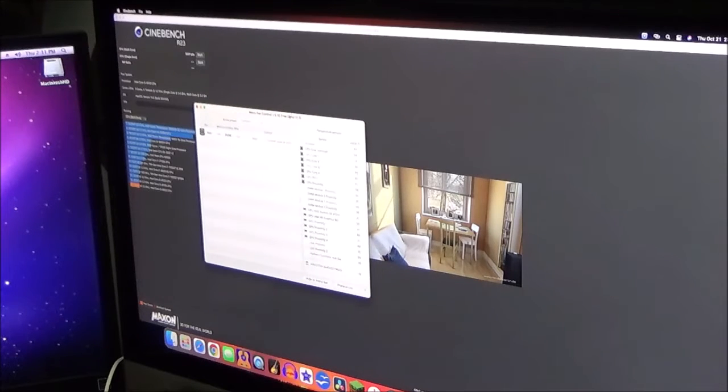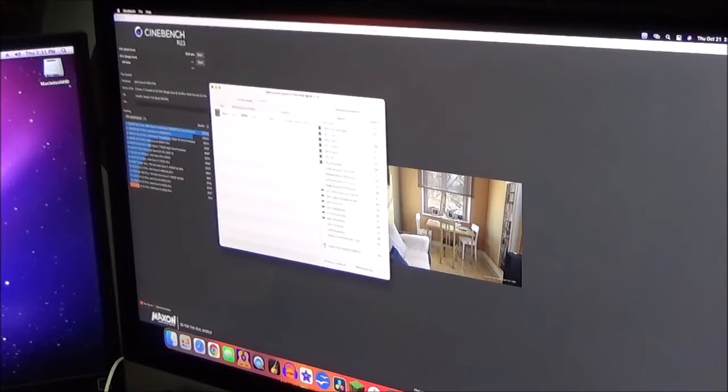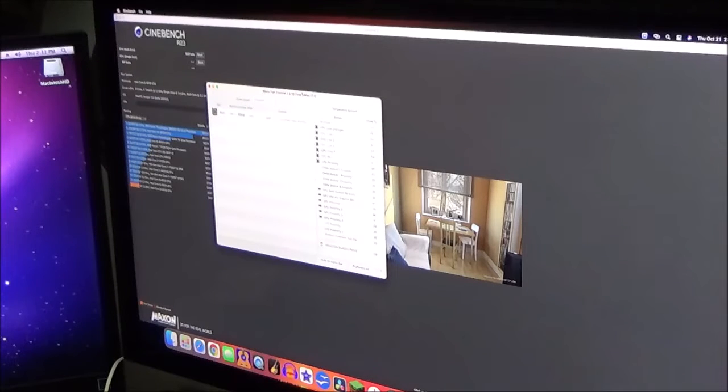Okay, looks like our test has completed with a final score of 3351. Average CPU temperatures seem to be around 75. Cores are in the 40s area, 40, 47, 48 kind of temperature. This thing is not thermal throttling. The fan is definitely doing its job. The system is starting to cool down rather quickly, which is good. We've already seen over a 20-degree decrease in only a matter of seconds. So I think as far as 2000 RPM goes, having the fan constantly at that area is definitely good.